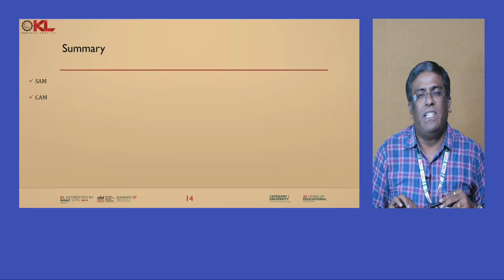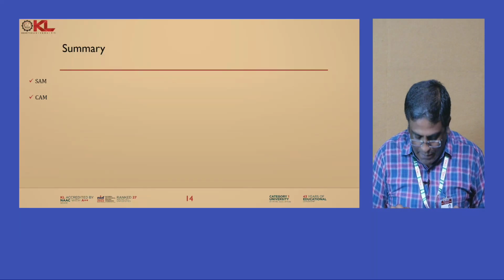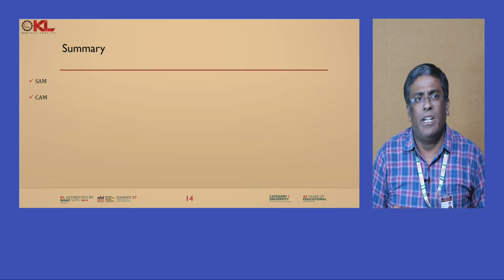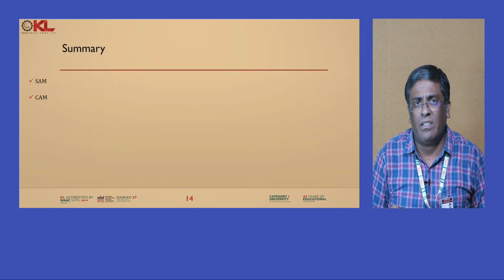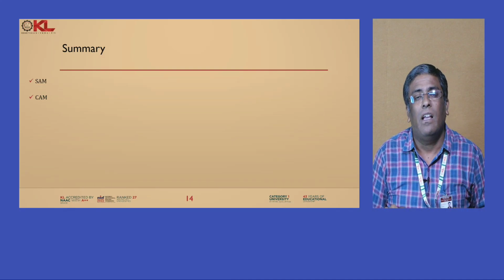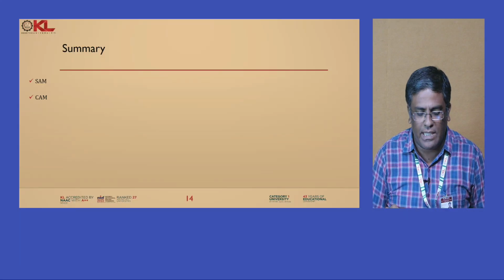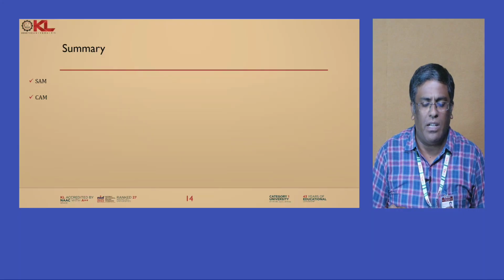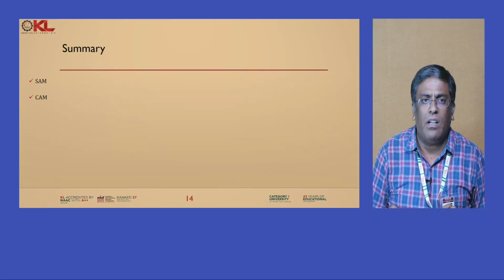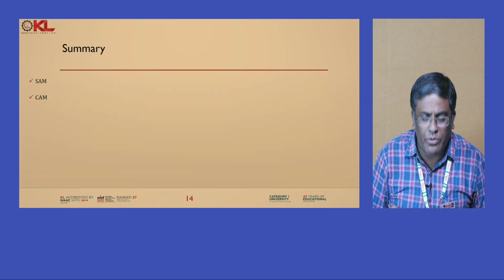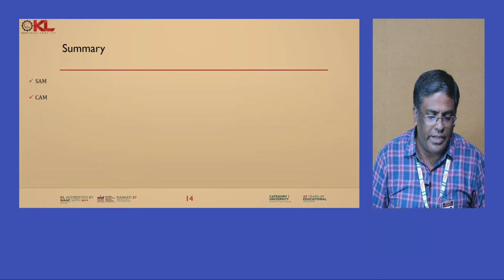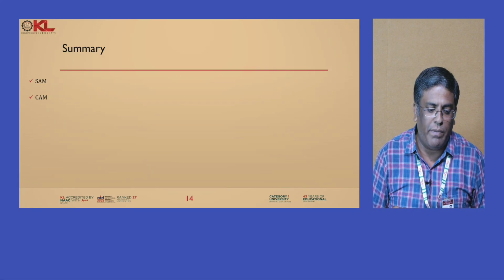So that's it. Just see how SAM and CAM are unique from traditional memory architecture. Remember, SAM is a serial access memory device and it doesn't require any address lines, and it adopts SIPO and PISO for a simple architecture. And CAM is different from traditional memory architecture because it's not using an address to search the data; rather, it uses the content available in the particular CAM device to access the address of the particular memory locations, and it is faster when compared with traditional memory architectures, right?